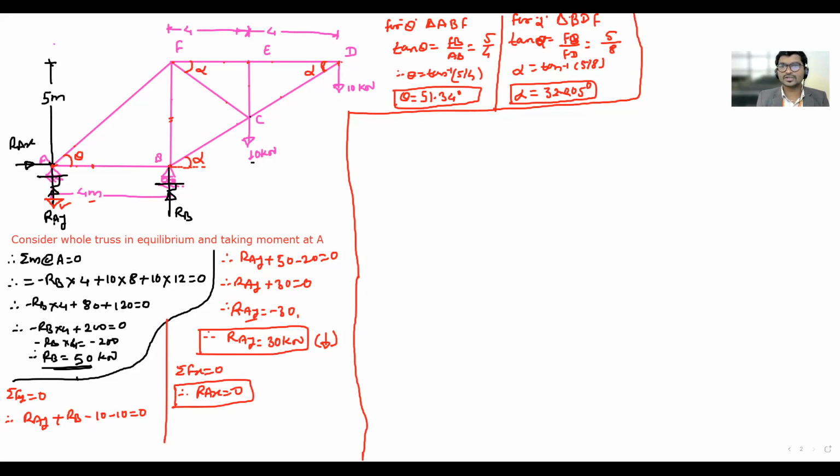Okay, so consider joint A for analysis. Draw dotted x and y axes. Always try to have dotted x and y axes. It gives us a base for which quadrant the forces and members lie in. I'm showing this one as Rx, which is 0.